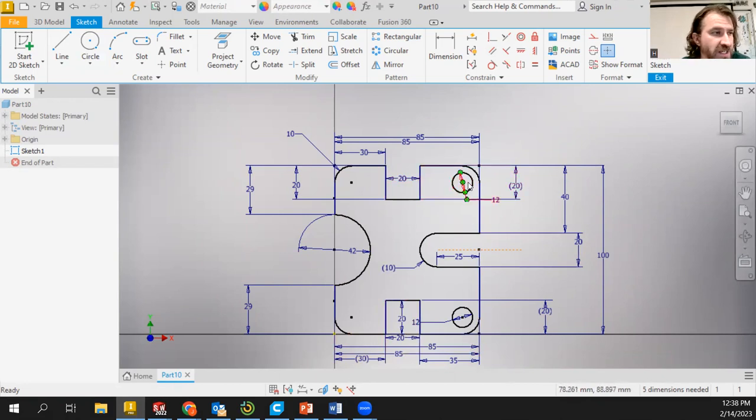The reason why we don't need to do any dimensions for these circles right now, like the horizontal and vertical, if you've been watching the other tutorials, you're like, hey, you're missing dimensions. We don't need them here because we use the center point of the fillet, of the curve fillet, right? If they're on the same center point, that is the position those circles need to be. And so it's in a good spot. We're absolutely fine. We just have to make sure our diameter is correct. So there it is. All right.